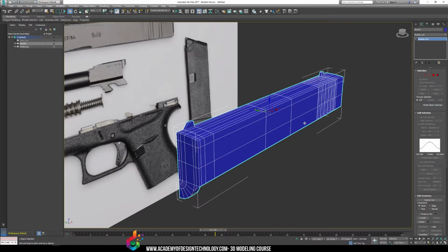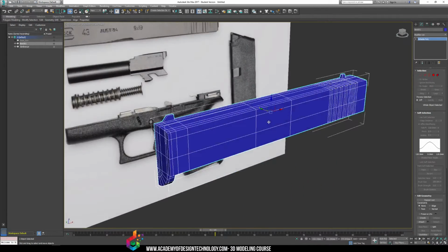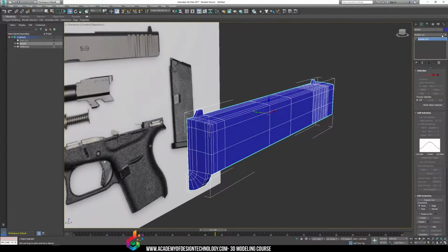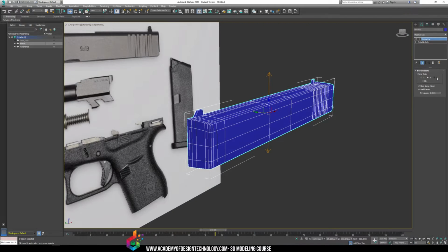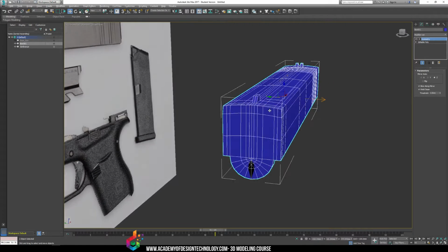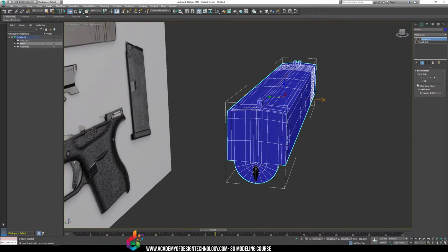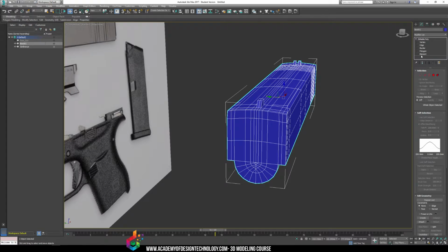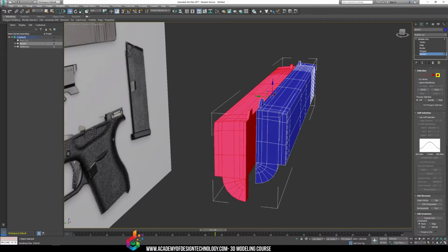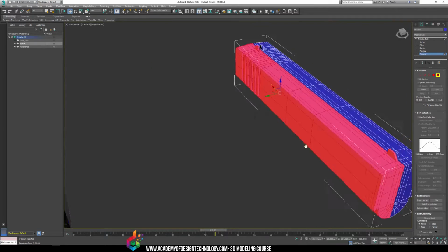and because this will automatically weld it for you, it might make it a little bit easier, make sure that your pivot point is right where this model is going to mirror itself, and you're going to add a modifier called symmetry. Symmetry just works like the mirror tool does, except it actually goes with your model, your current model, the way it is. And we can adjust it, we can flip it, we can slice along mirror, we can tell it to weld the seams automatically, and we can give it a measurement, or we can tell it not to weld the seams, and we can collapse it. And you can see we get an exact duplicate right beside each other, but not welded right now, which is fine. We're going to leave it unwelded for now.